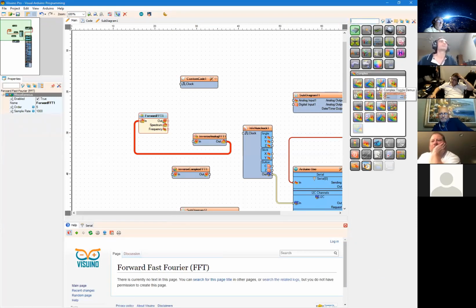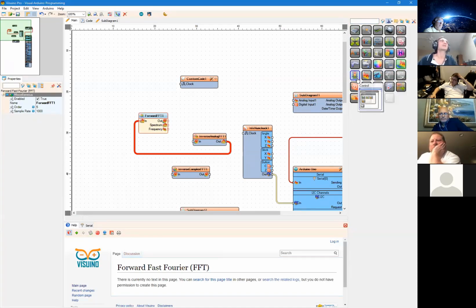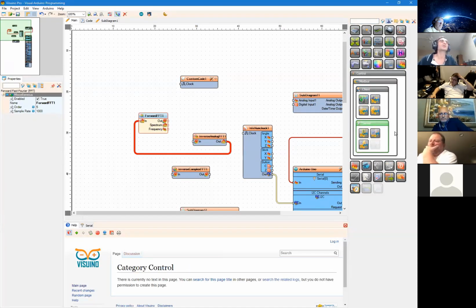But that's not all. The final goodie is that the Pro version comes with full-blown Modbus support, TCP and serial, both ASCII and RTU. So you can do industrial automation SCADA control. I mean, you can control industrial automation SCADA controllers from Arduino itself, or you can implement your own PLC controller inside Arduino and deploy it in industrial environment and use control software to control your Arduino.